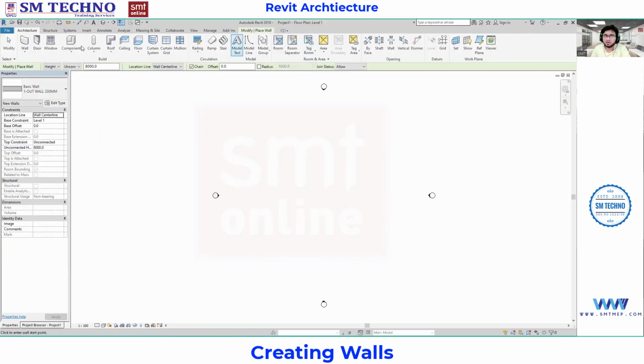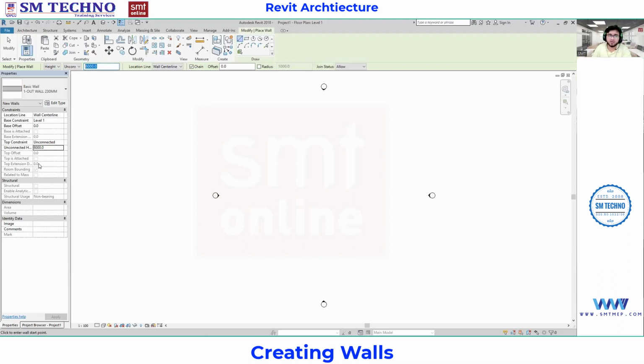Now, the same option. If you want, you can see now we have got the outer wall. Now provide the height. What is the height of the wall you want? In the options bar, you can specify, or else in the properties also. Like I have given the height of something like 3000 mm.